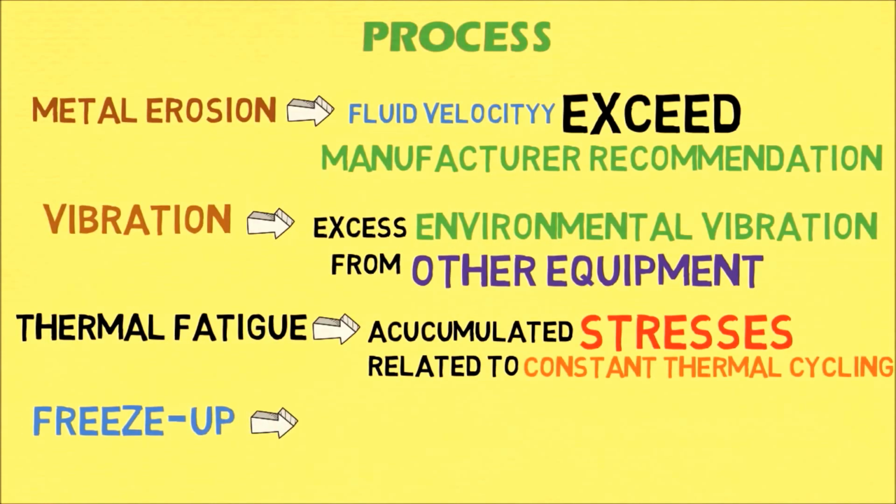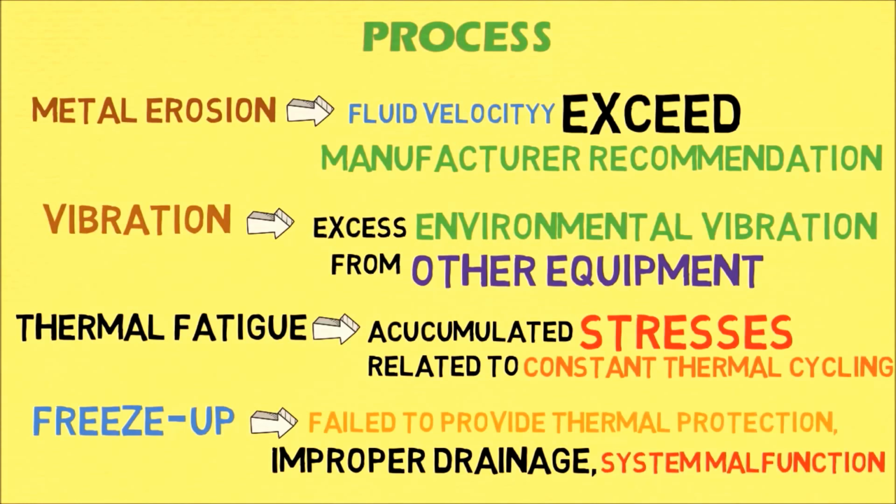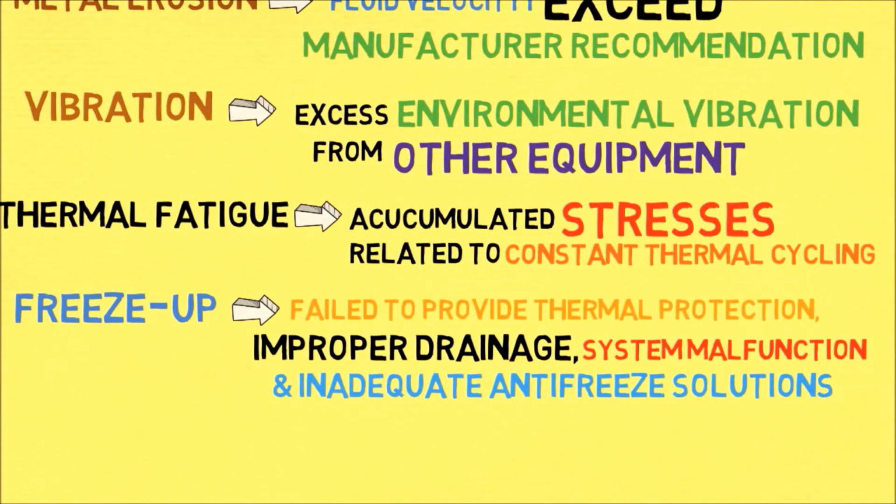Freeze up is a result of the operator failing to provide thermal protection from the elements, improper drainage during a seasonal shutdown, malfunction of a thermal protection system or heater, or inadequate antifreeze solution.